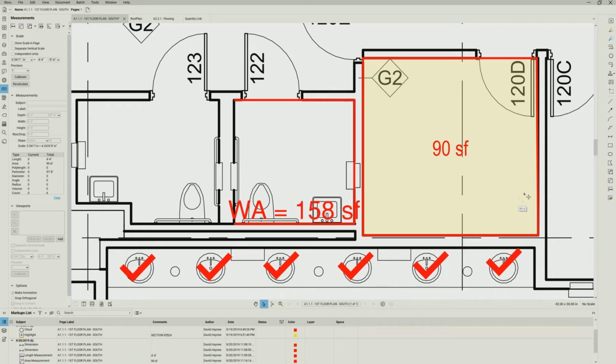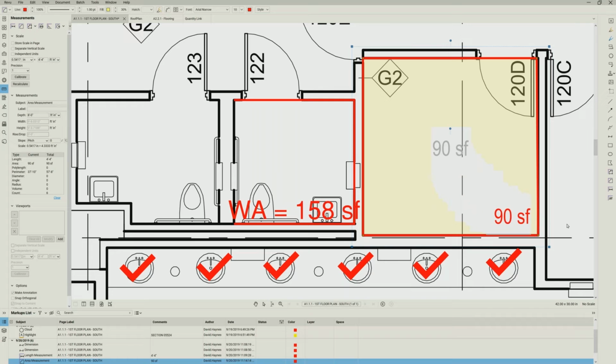Another tip that I'd like to show you is often people ask me about, well, I want to move this. So I'm going to tell you what I do because you'd have to be looking at the keyboard. I select the markup. I put my cursor right here, not up here at the dot, that just rotates, but right here where the takeoff is, I use my shift key down and hold it down, and now I can move this where I'd like to move it to. All right, just a little tip there.